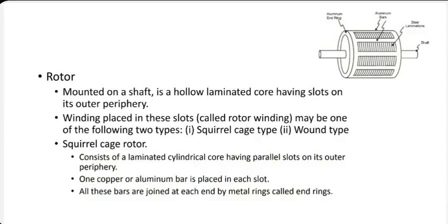By the way, single phase version of induction motor is what we are using in our ceiling fans all the time. The construction that we use is known as squirrel cage construction. Instead of having thin conductors on the rotor, we make them solid aluminum bars, as shown in this diagram on the right hand side of this slide. And this is a very rugged construction. These fans can fall even 40 feet and still the damage done will be very small.